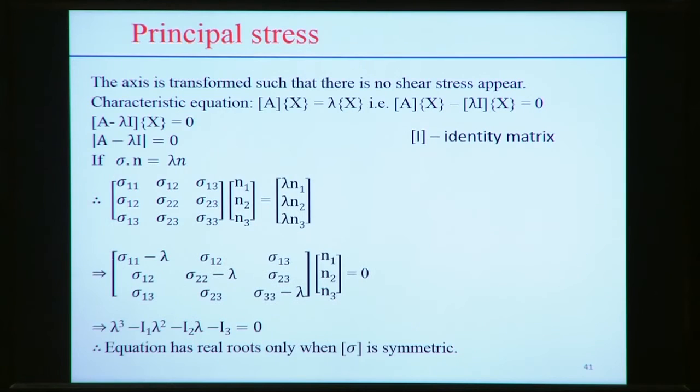Now we can go back to the case of a three-dimensional stress state, and how we can find the principal stresses. Like two-dimensional cases, we have already discussed that there must exist some principal stresses, in the sense of maximum and minimum stress values, when there doesn't exist any shear stress. But in three-dimensional stress, we can find the principal stresses in a very straightforward way.